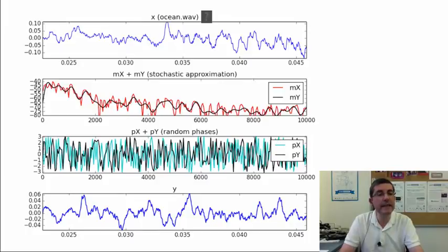Okay, and then if we take the inverse Fourier transform of these two black lines, of the approximation of the magnitude and the random phases, we get this output signal, and we are claiming that perceptually this signal is going to be similar to the first one. Of course, by looking at it, that might not seem to be the case because it's clearly a different shape, but given that we're talking about stochastic signals, the details of the shape are not relevant.